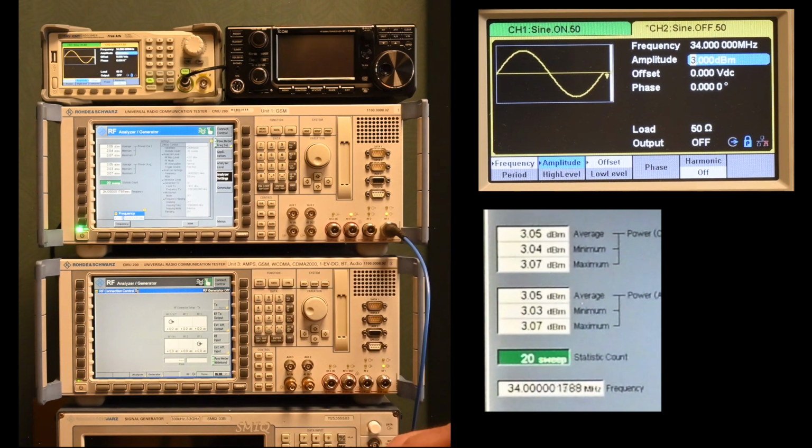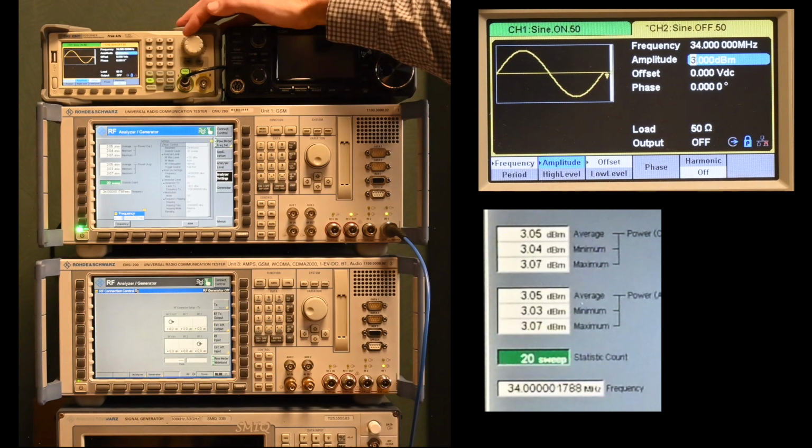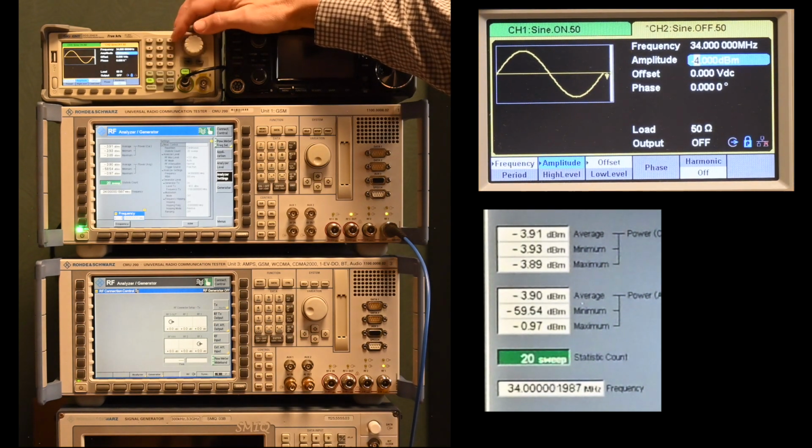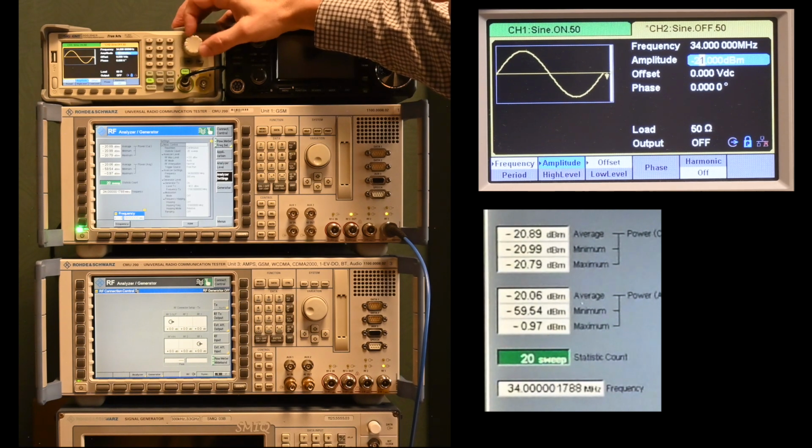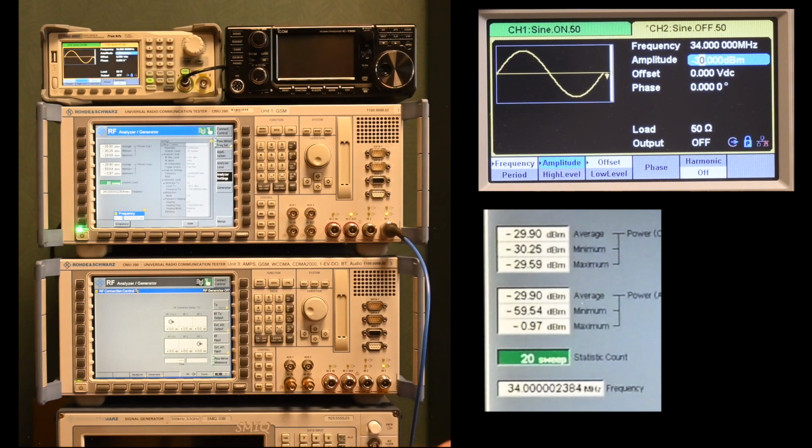And as you might have guessed, this method is much more sensitive. So if we go to much lower values, let's just go to something like, I don't know how low my unit is bringing me here, but minus 30 dB. Yeah, so we've got minus 30 dBm. Sometimes I say dB, but it's dBm, of course. We're working here in power levels, not relative levels. So far the selective power meter is functioning just as you would expect in the CMU.